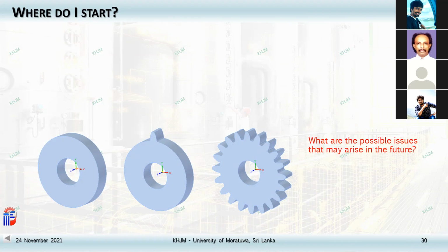And also you should have some idea about the minimum number of teeth that you can have. You have two standard pressure angles, 20, and another one is I think 14.5. And also the maximum gear reduction, or even a step up. Can I get something like 1 to say 75, 80, or even 100? All these things you need to check. There are recommended values as well.